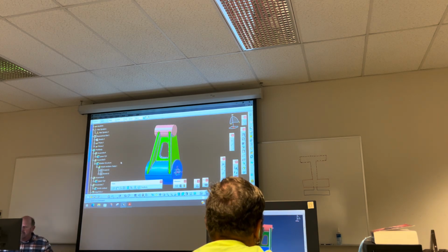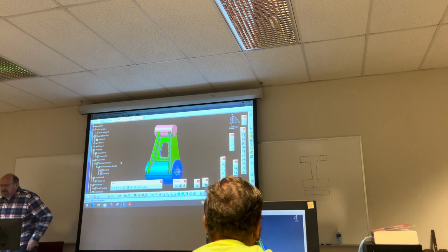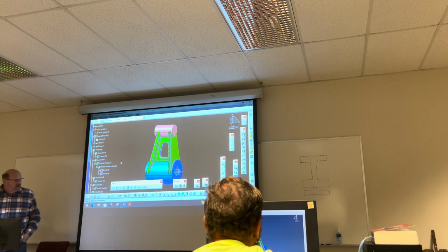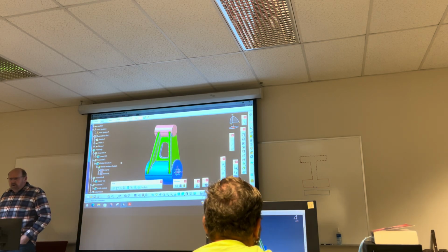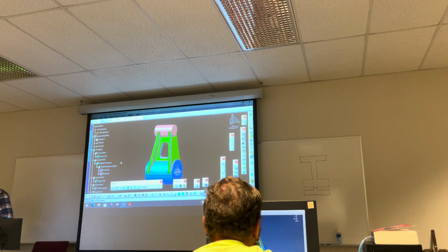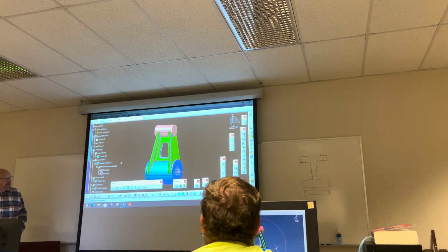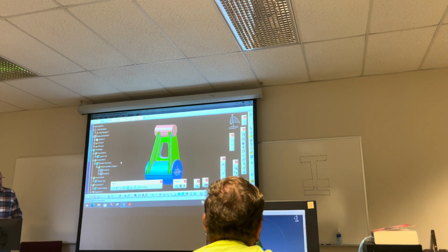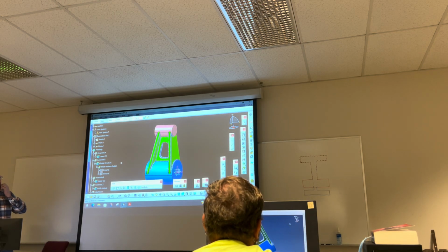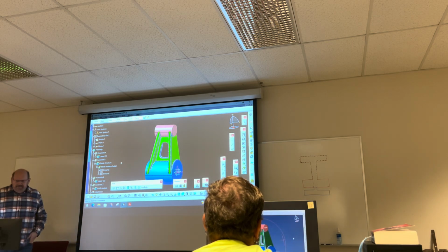All right, before I actually give you the drawings for this and the other ones, OBJ 100 and OBJ 101, questions on this? A lot of details to it, but if you follow some of the sketches, the multi-section solid works really good. You just gotta make sure that you got good tangencies, that your sketches are robust enough to build it.